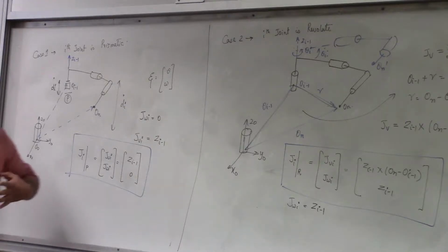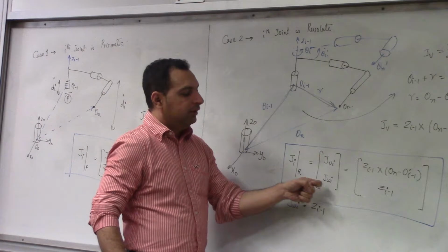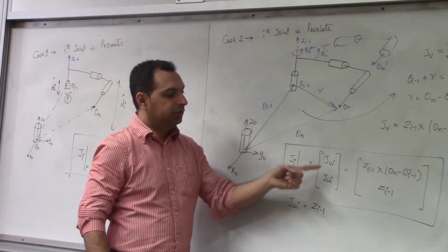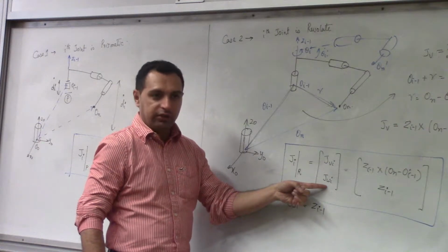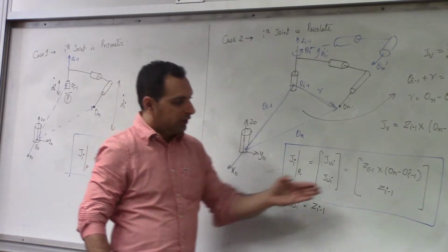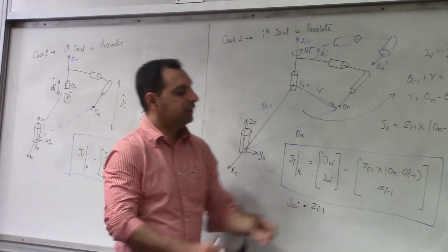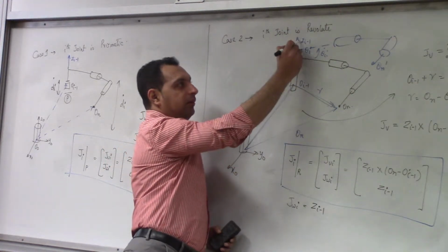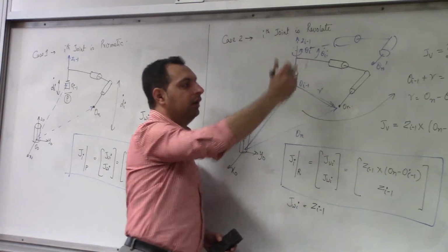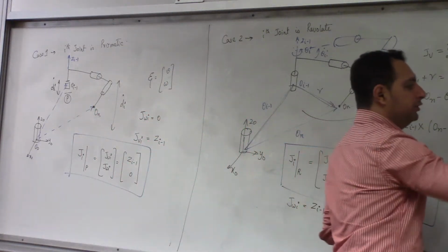So basically what we are trying to do is this j omega. Obviously you have to understand that any revolute or any rotational motion will generate both linear and angular velocities. We need to know if there is a linear motion, about what axis it is, and if there is a revolute motion, about what axis. So revolute is obviously about this axis, because that is how it is defined. You choose an axis for theta I, which is the axis about which you generate motion.